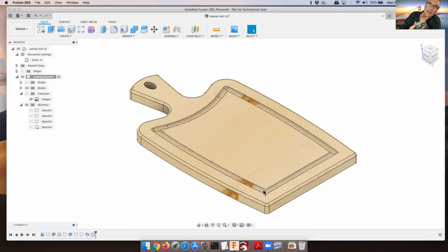So you knew where it was in, and you were just placing it in the same place. If you had been on a different view, you might have been able to say, make the center coincident with this line. Yeah, and you may have reasons to force a slightly different offset. Like if we look at it right now, here's the profile, and here's the path. One thing that's a bit magical here in Fusion 360 is it went with the nearest point to start.